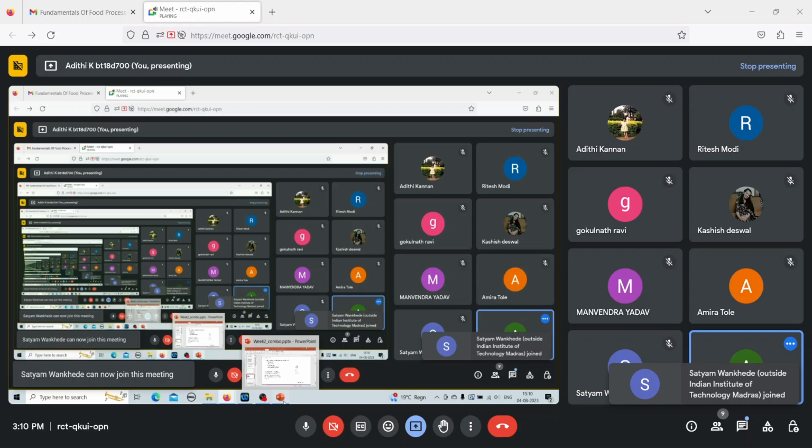Sorry, you have minus t by tau, so it will become minus 1. Is this clear? t naught goes to 0, t we are substituting as tau. So you have sigma equals sigma naught exponent of minus 1. And 1 by e is 0.368. So your sigma is equal to 0.368 of sigma naught when t is equal to tau.